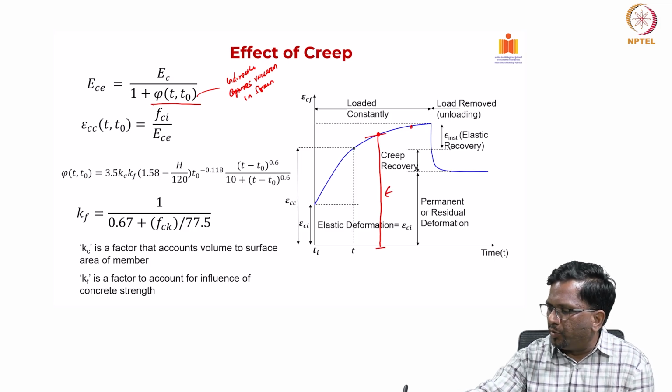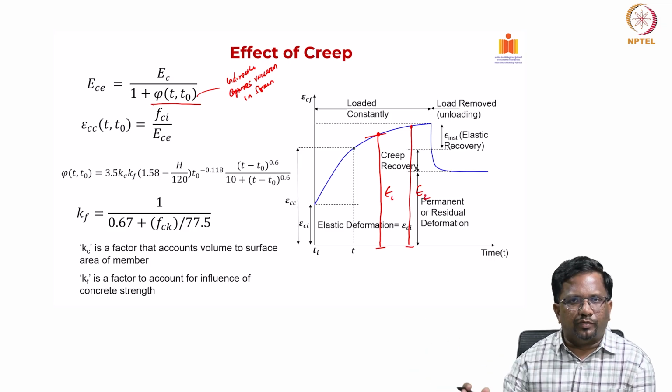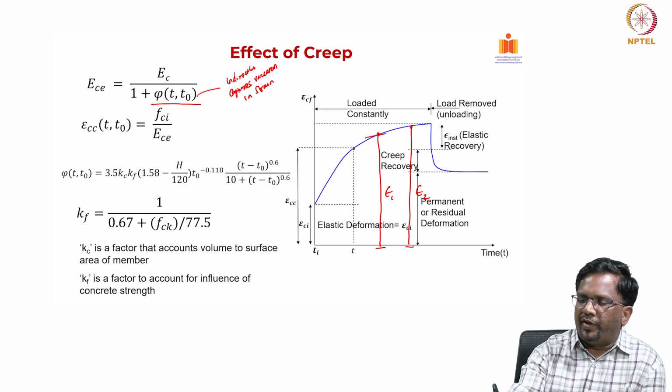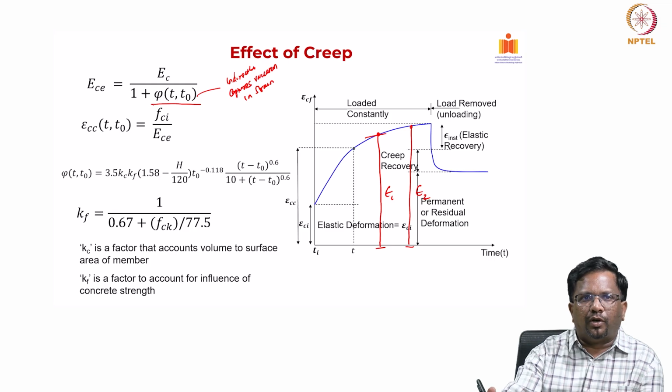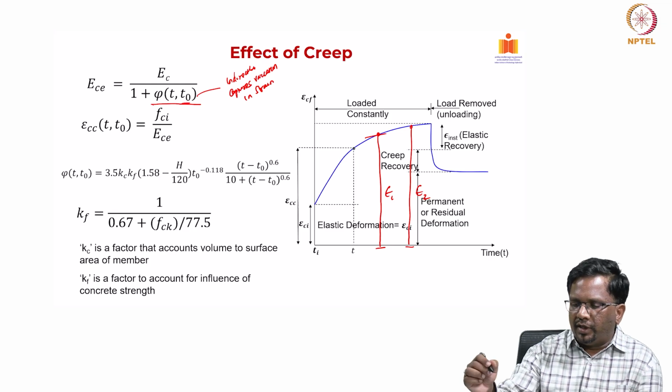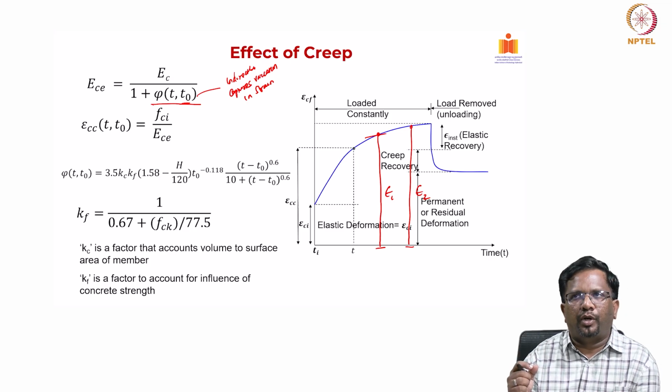If I take at this point, this is my strain. So somehow I have to account epsilon 1, epsilon 2. Account for this variation in strain depending upon what time that I am dealing with, right. So the phi should be function of time t, and there is also something called T0. T0 is the initial age at which that I am going to stop curing.